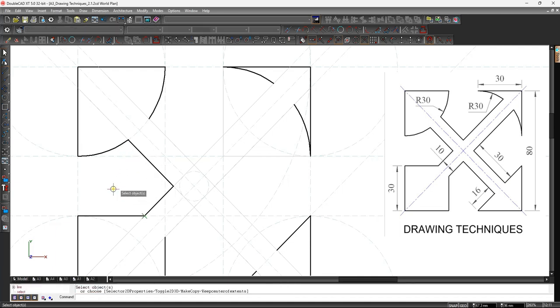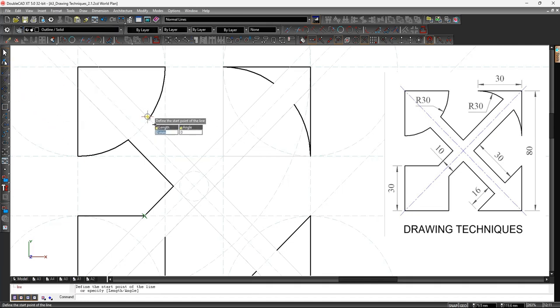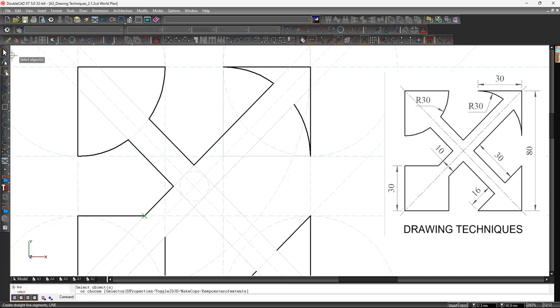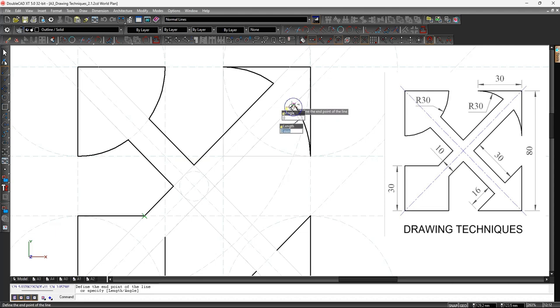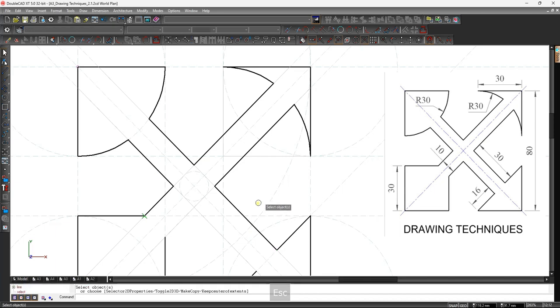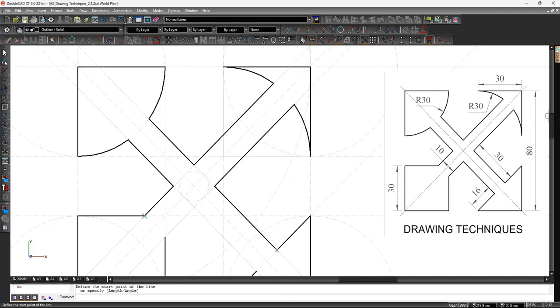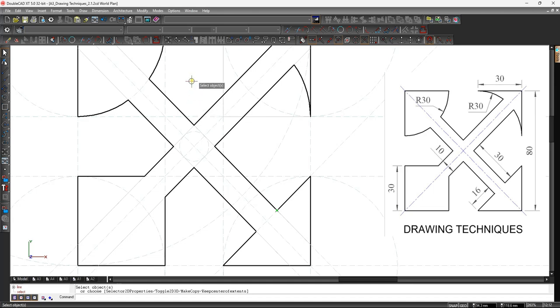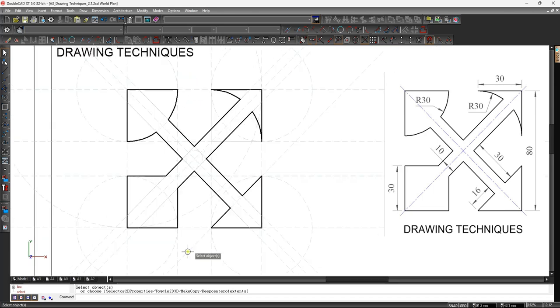On paper you can now draw in those lines solid with your instruments. I'm going to again select the line tool, snap to those reference points and draw the desired lines up to where I need it. Once I finish there, I escape, select the line tool again from the reference point to the intersections, and once I'm done I press escape out of that, do the final one. So from here to there and finish off on that one. Let's zoom out, and now we have duplicated our reference image.